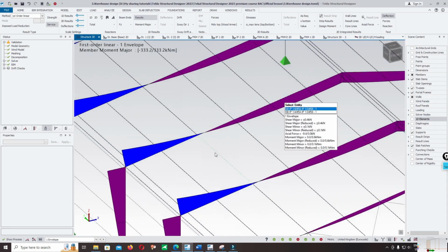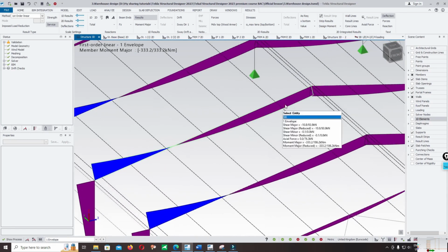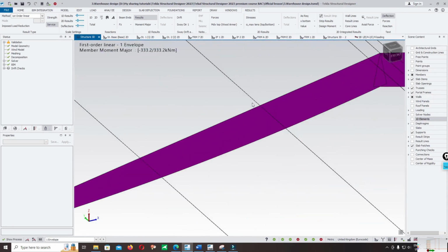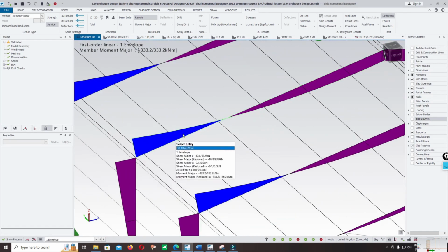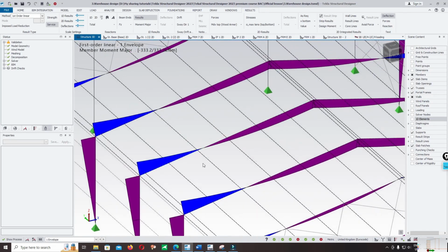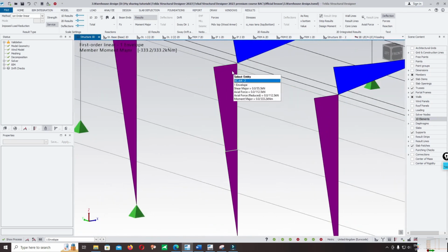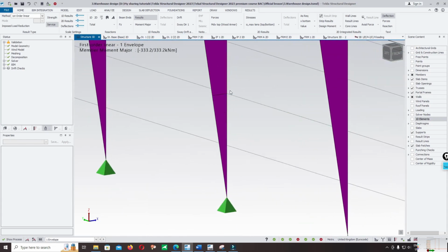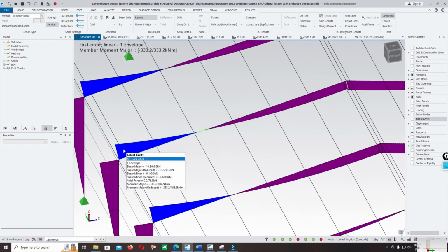In compression, we can add the torsional restraint in the location, and for the location you can add at the intersection. It's optional, but in my design code I add it at all intersections of the purlin with the rafter. For the column it's the same, we add it at the maximum moment location, so you can add torsional restraint. For the location you can add or not, it depends on you to verify and check it. And for the rafter it's the same.